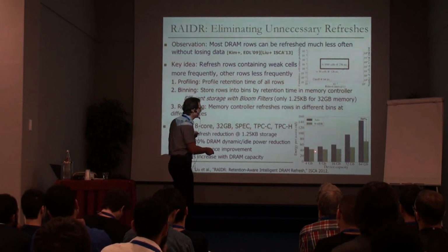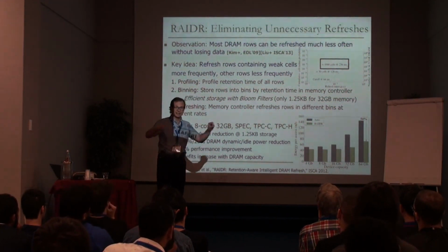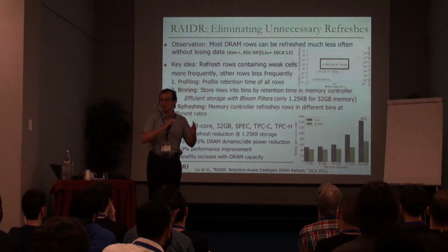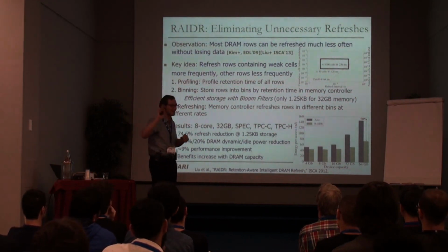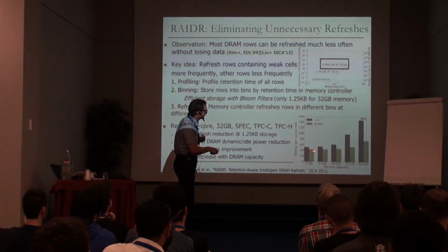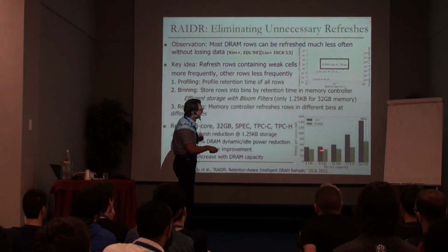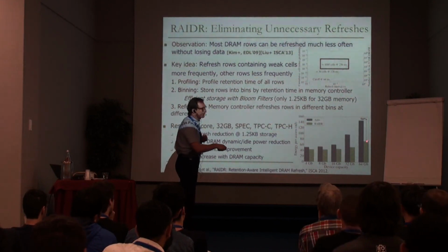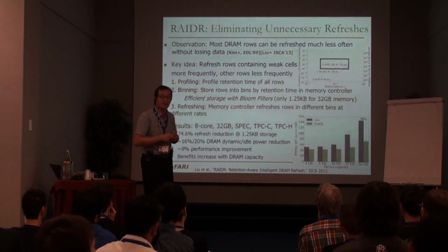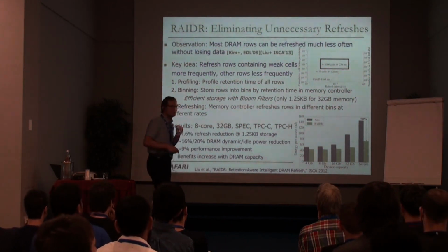But if you look at this curve, ideally when you increase the size of the chip, you would like the energy per access to be constant. Well, ideally you would like it lower, of course, but maybe that's too ideal. Ideally you would like that energy per access to be constant. This is the green part over here with RAIDR. It turns out even RAIDR is not enough if you have a chip that's very large. So you really need more techniques to be developed to solve the refresh problem.